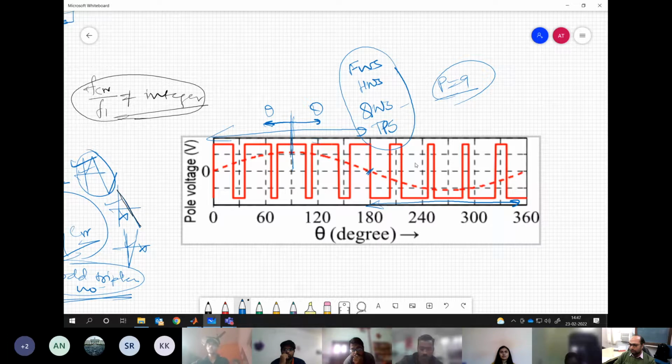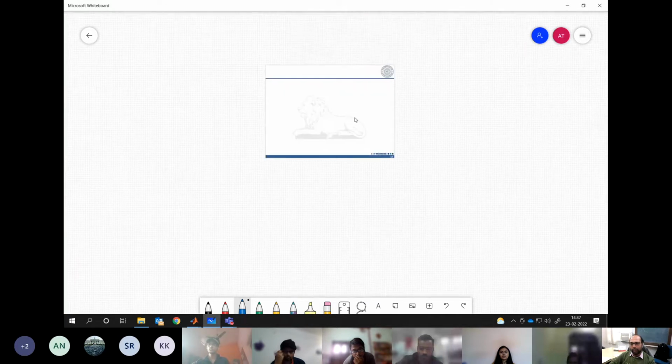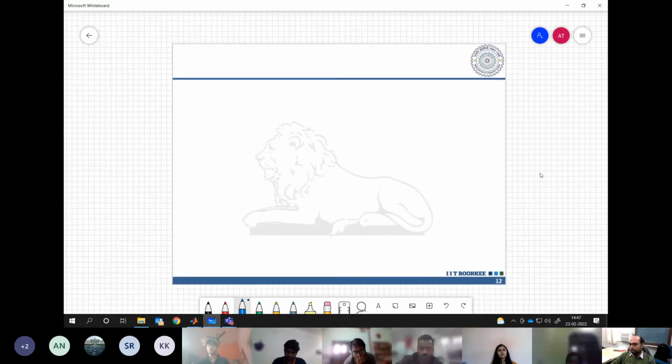Yes, sir. Correct. Now this is where we move towards the analysis of sine triangle PWM. What do I mean by analysis? Whenever we have any PWM, we should know the quality of that PWM, how it is going to perform. And when we had low switching frequency PWM, what was the metric for performance? What metrics or parameters are we using to judge everything? What is the performance criteria? Weighted THD is one thing, but finally, what we are trying to have is, how is the current THD?